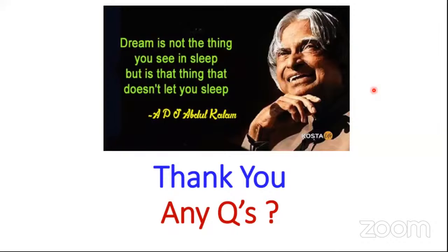Question from Mr. Sandeep is, is there any chance of stress development in the part, like residual stresses? Definitely yes, because the process is very similar to the welding process, if I can give the analogy. So obviously you will see that we do a lot of fixturing when we do a welding process. If we don't do fixturing, you will see distortion or warpage of the weld plate, be it a lap joint or a butt joint, right?